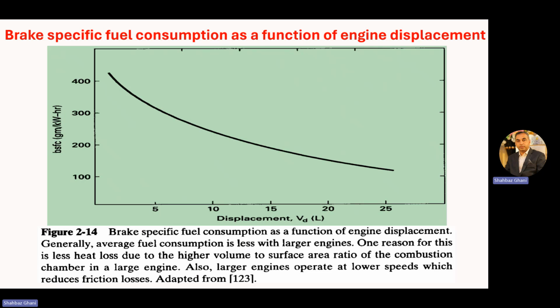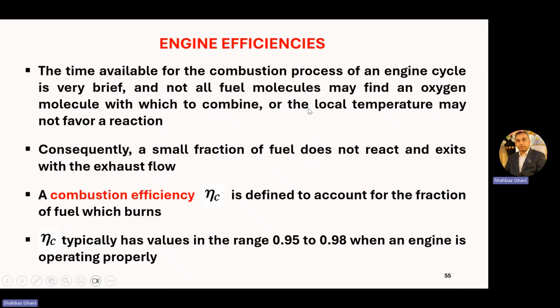When the displacement is small, you have a higher brake specific fuel consumption. As the volume increases, the brake specific fuel consumption decreases. Now, another important operating characteristic is the engine efficiencies.